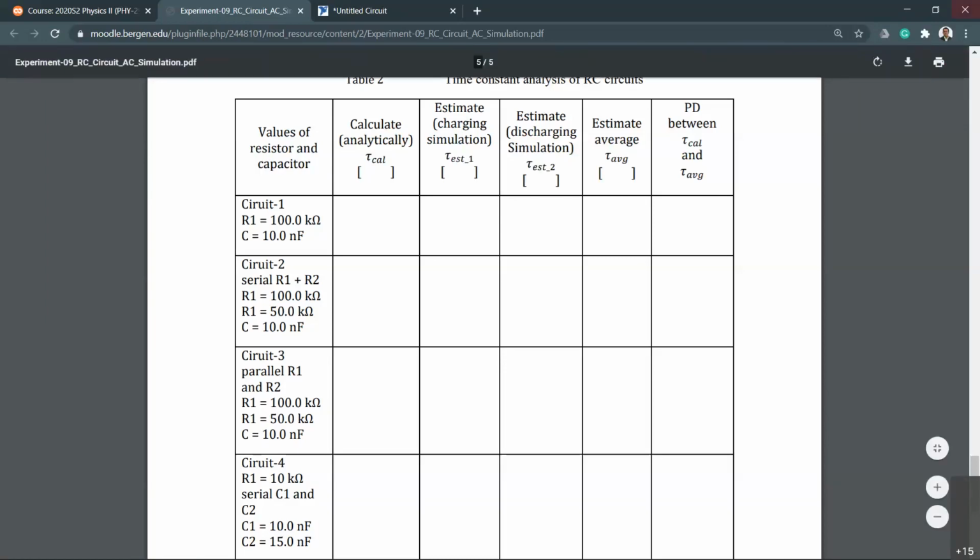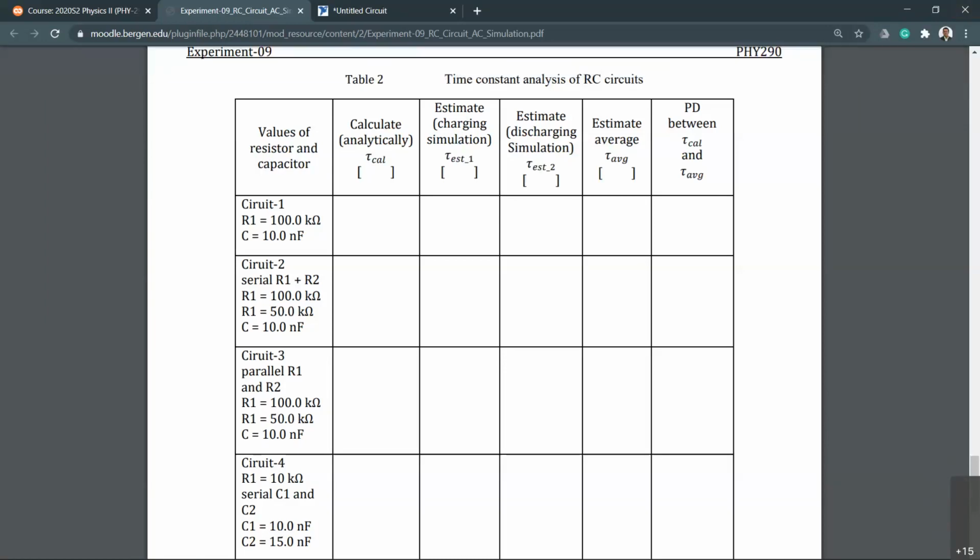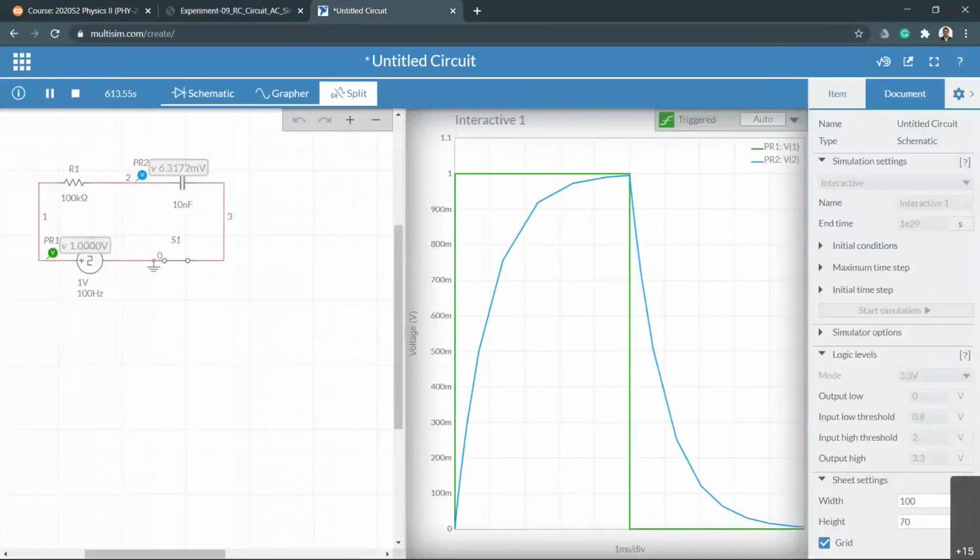Okay, then let's continue. Let's take a look at how to do the analysis part. Anybody have any problem? Everybody have the circuit? Good? It's working fine? Make sure all these numbers are properly adjusted, okay? If you don't see the graph, one quick thing to check is the numbers: whether you have the right resistor value, capacitor value, and frequency. All of those matter, okay? If anything changes, your graph will not be easily analyzed, okay? All right, any question?